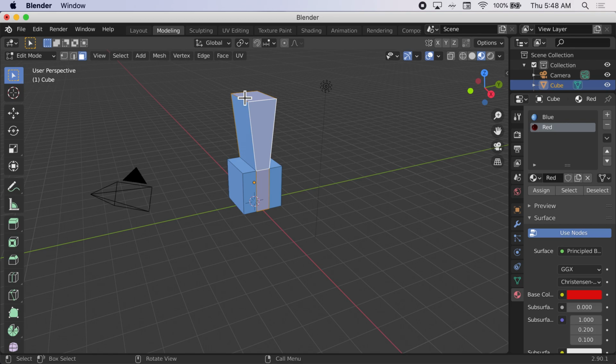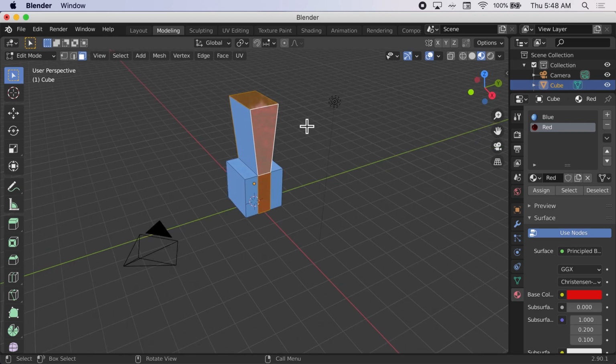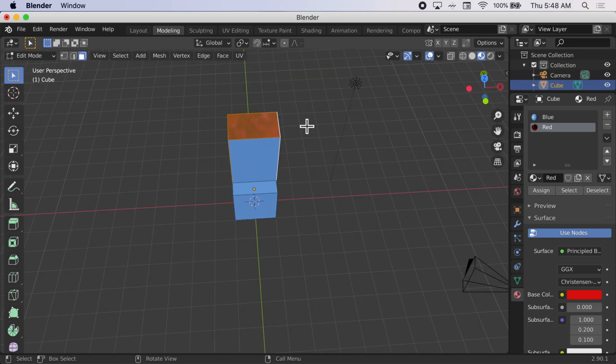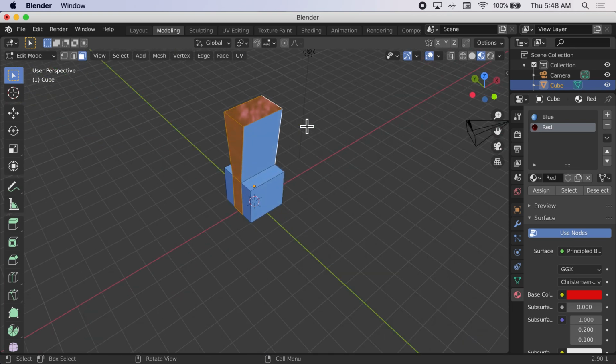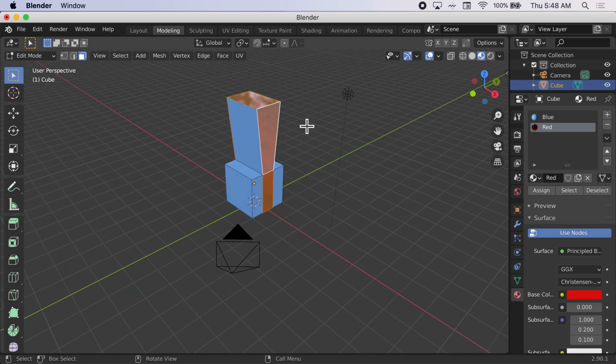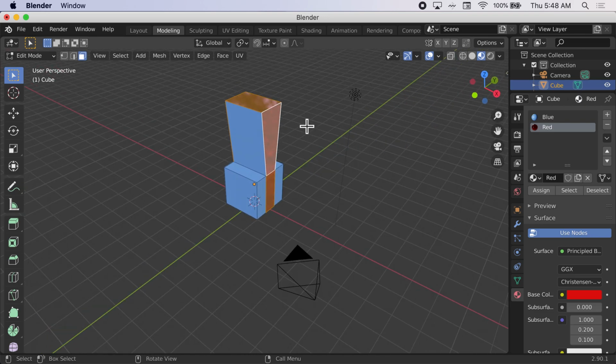And again, with this center of faces around this object selected the whole way around, and we select red over here on the right, we're going to then click assign, and now that assigns that metallic red that we've made, because we defined it as being metallic and specular and all that. Now that is assigned to those faces of the object.